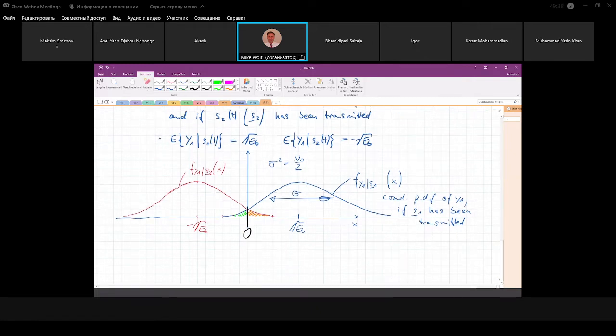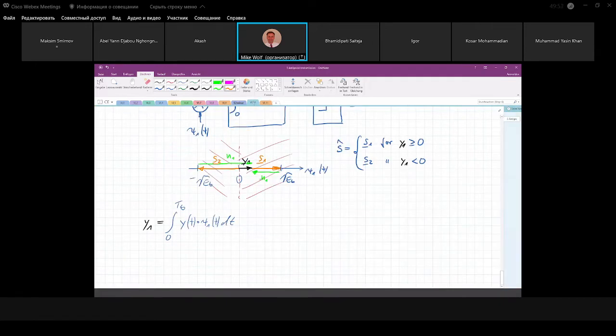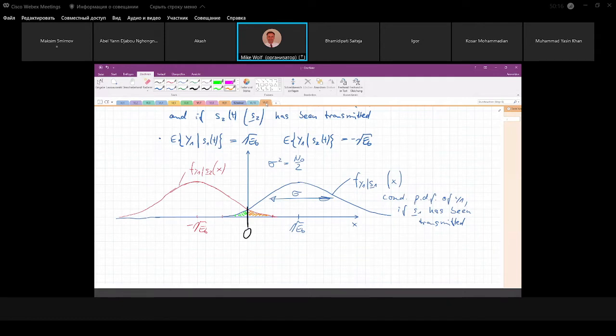And again, remember our noise vector: a larger noise vector means a lower probability, a vector with a lower length. Remember this figure. So we would choose S1 for this case, because in this case the noise vector would be shorter than in this case. This just comes from statistics. If we didn't have this Gaussian distributed noise, this wouldn't be as simple, but now it's clear. And now we can calculate the bit error, and we can write the bit.